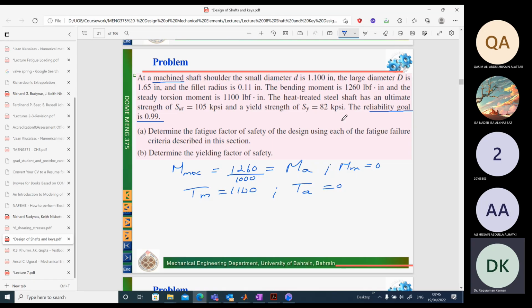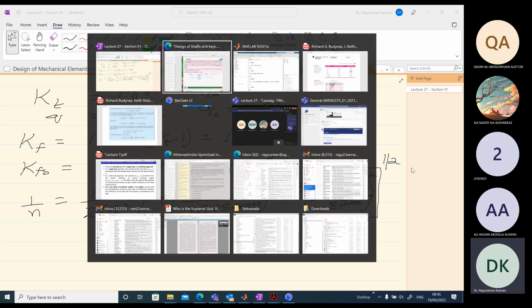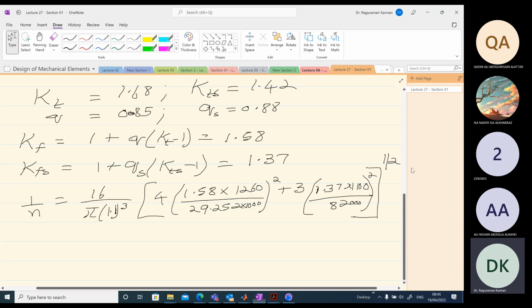The properties are in kilopounds, while the forces are in just pounds. So there is a factor of 1000 over here. So we need to include those factors in the denominator. Then it would come out right, or multiply the properties by 1000. Either way, this is correct.